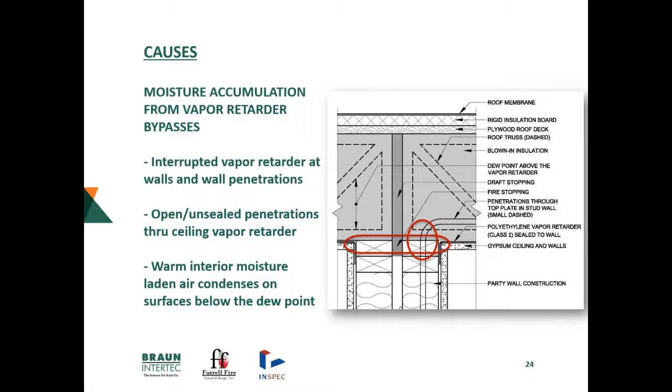So what's causing these situations of moisture accumulation? Well, as Steve mentioned, it's pretty much determined, at least through the test openings we've done, that these vapor retarder interruptions and lack of sealant, and such openings creating these areas for air to transfer up into the space, are really the culprit. And of course, hitting that dew point somewhere in that section where that cellulose is in that concealed space.